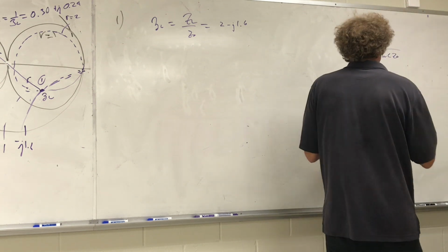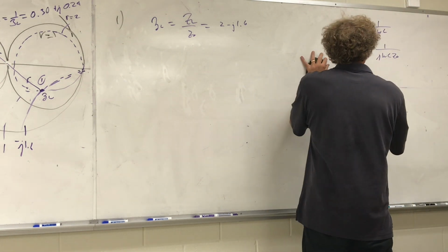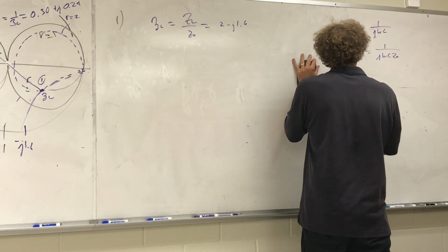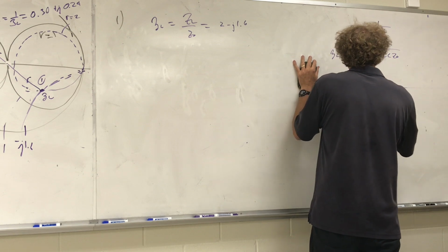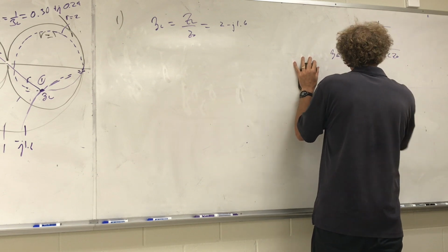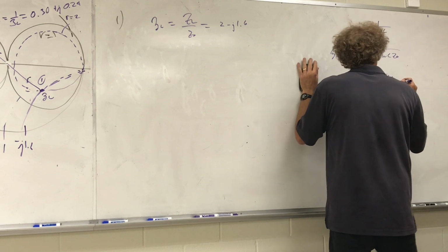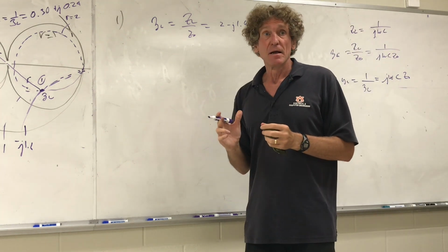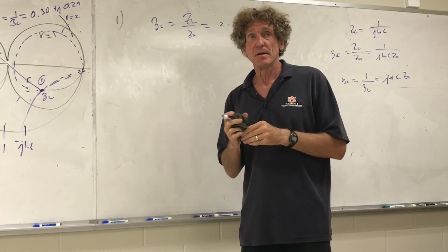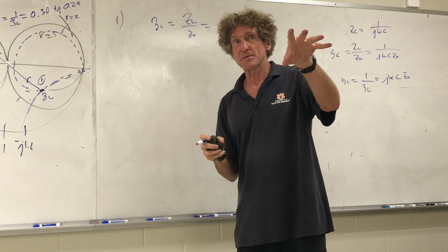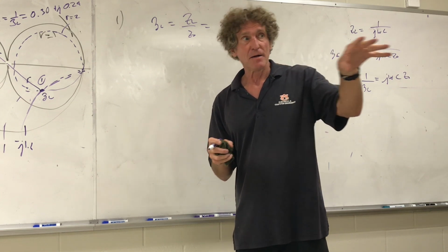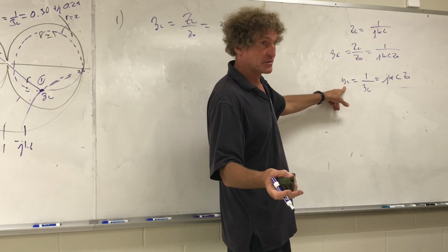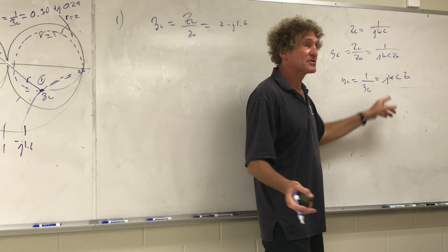Now, that's the normalized impedance. The normalized admittance, I'll just call this small zc. Yc is going to be 1 over zc, and that would be J omega C times Z naught. Does everybody agree with that? Everybody? Y'all follow me? In the back, you guys with me on this or not? I'm just making sure. Now, that's the normalized capacitive admittance, right? You'll notice it's plus J.